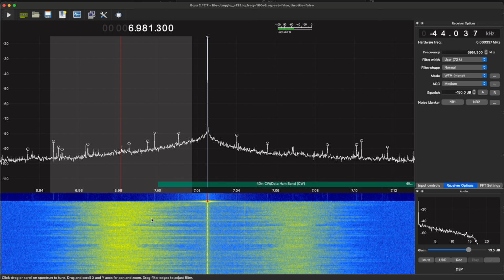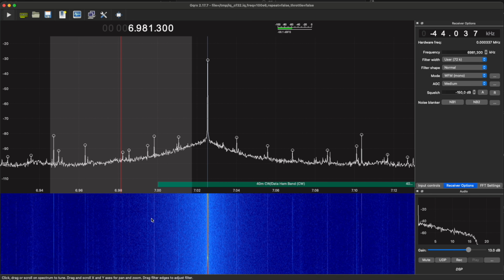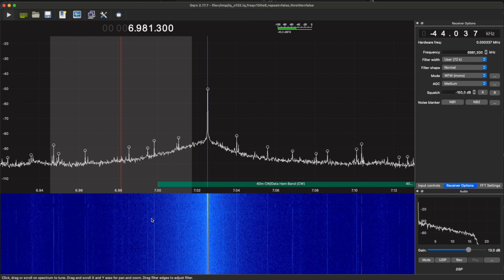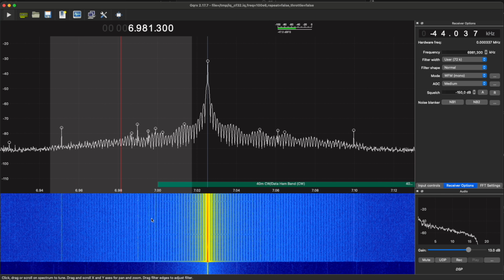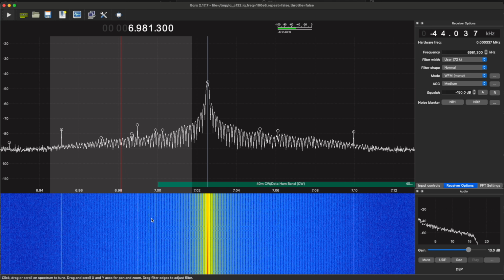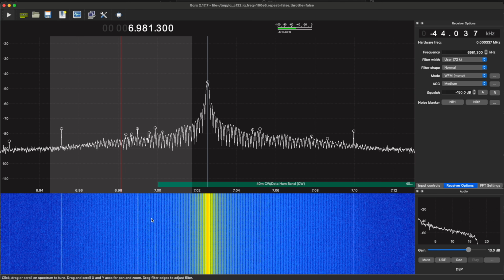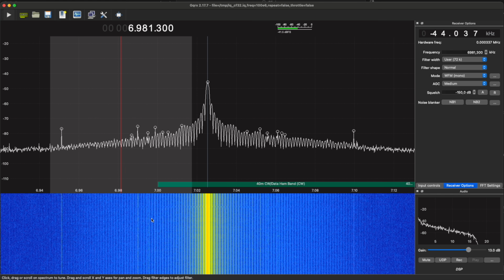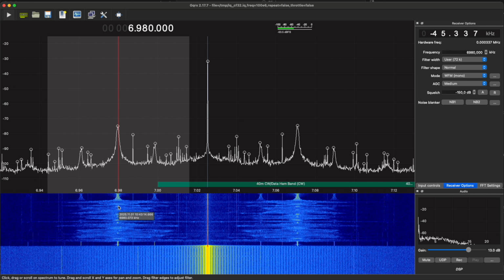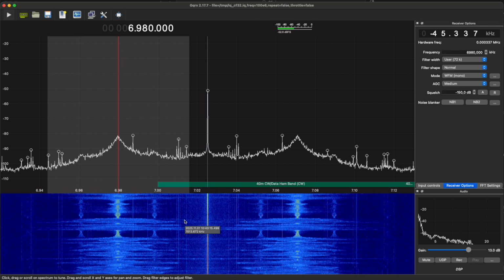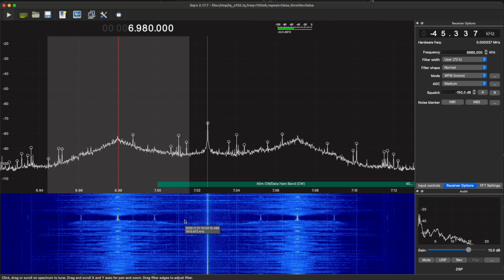The coolest thing about this is that the SI5351 tunes reliably to frequencies around 100 MHz and handles the 90-degree offset into the mixer. Mixing down 100 MHz to baseband directly is quite a bit better than I expected. Going up to 144.8 MHz, as you see here, doesn't work so well though. But I can't tell if it's because the synthesizer can't keep up, or because it's close to double the PLL frequency of the STM32 F103 at 72 MHz.